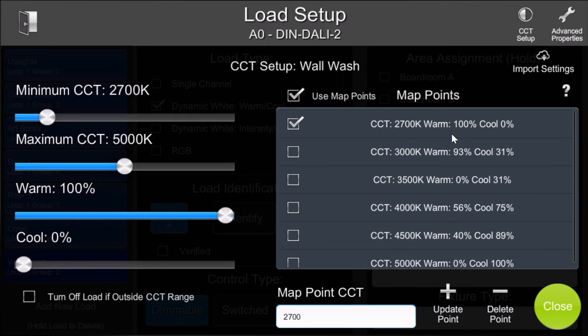That one didn't capture. So you do need to set these sliders first before it'll capture them. If it has old values, it would get the incorrect value. So do make sure that you set these sliders, which is something you're going to have to do anyway. So that concludes setting up this particular fixture for CCT calibration.